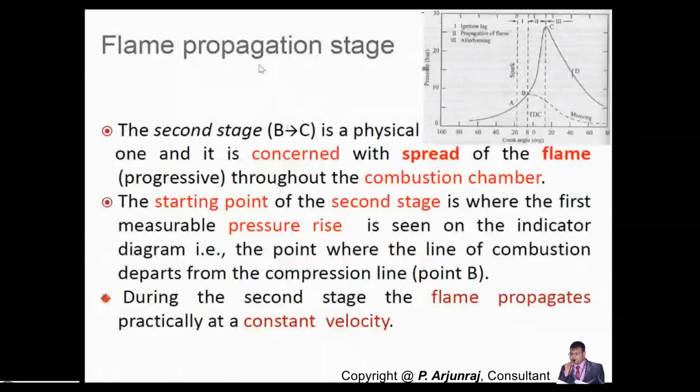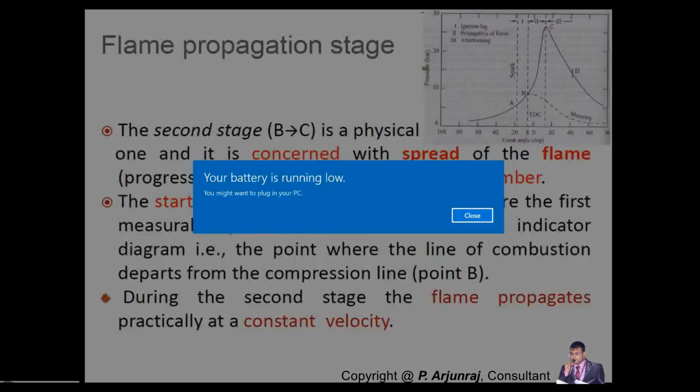So B2C is nothing but the flame combustion stage, and here the flame is going to spread throughout the combustion chamber, down to the surface of the piston, from the surface where it started the propagation. Let's see the propagation. This is the starting point.